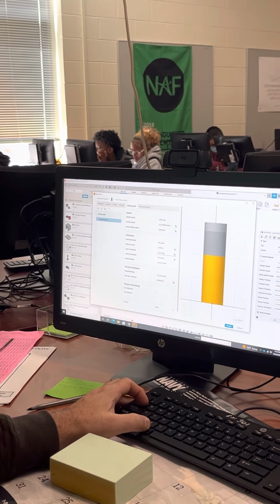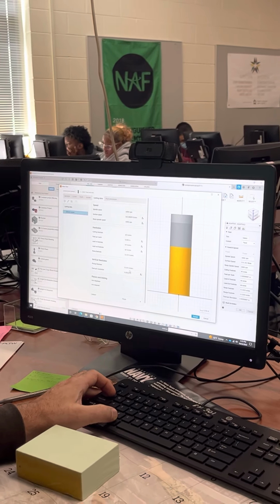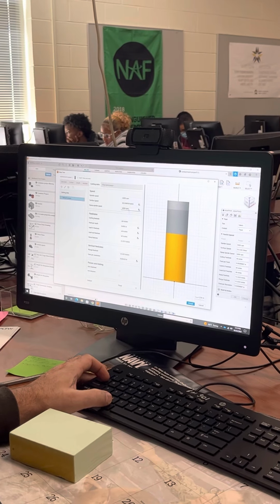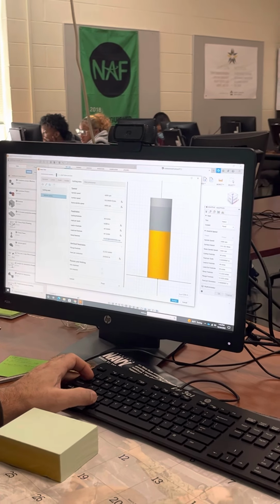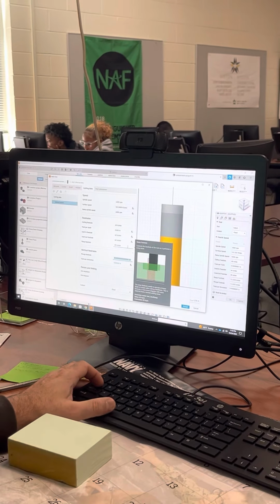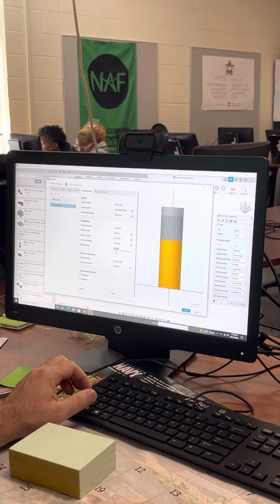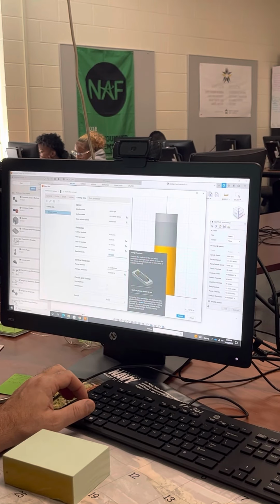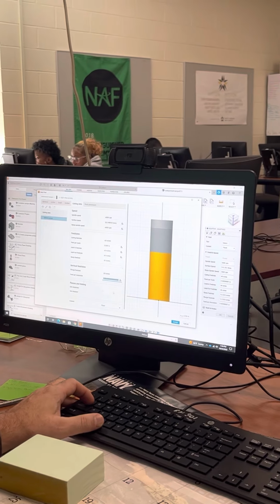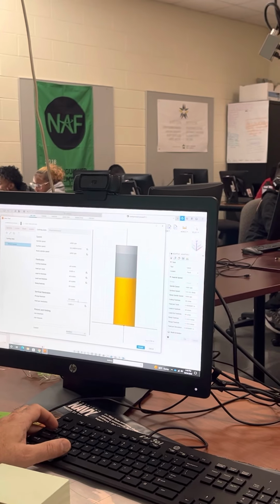Beat per, these are all functions, so you don't have to change that. Plunge feed, plunge should be half the feed rate, so we could bring that up to 20 inches per minute. Oh yeah, and ramp feed can be the same thing. Yeah, that's fine. Plunge 20. Feed per revolution, that's a function. And then coolant off, disabled.